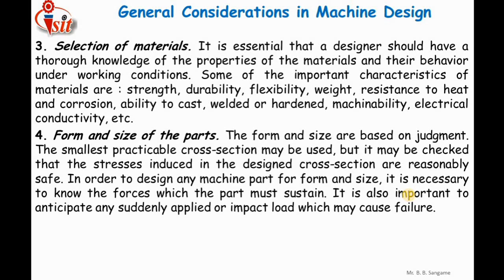In many machine components, the form and size of the part matters, for example in an automobile, a car. In that case, sometimes because of aesthetic and ergonomic characteristics, or because of the looks, we might have to go for a lower cross sectional area. Any component which will be safe for the lower cross sectional area will obviously be safe for the higher cross sectional area. So while selecting a form, shape and size, a designer should consider the loads acting on that component, because sometimes because of the looks or external appearance, the shape, size and thickness of the component get reduced.